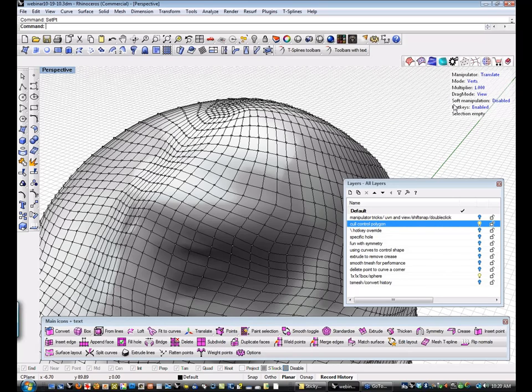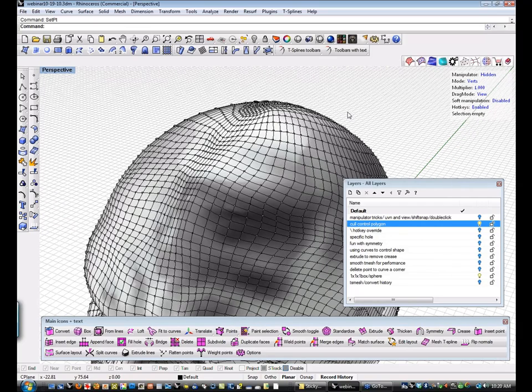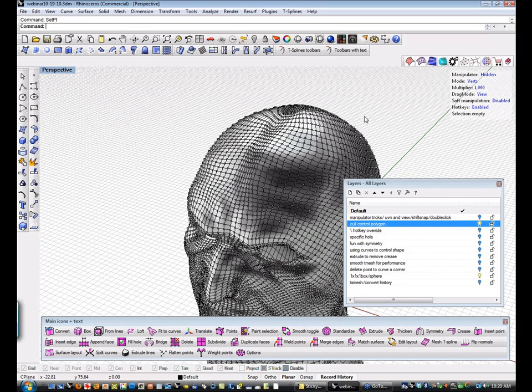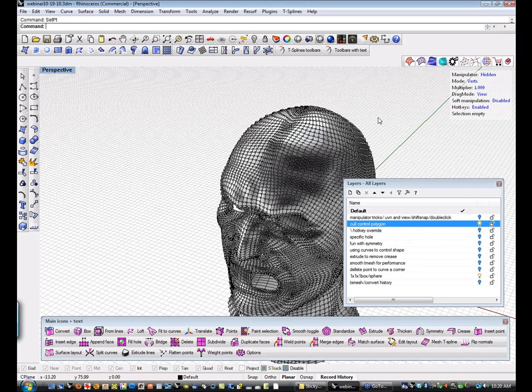The other way to do that is to hit control space bar, which shuts off the heads-up display, enter your Rhino keys, control space bar, bring your heads-up display back up, and that changes the priority between whose hotkeys are working. But the backslash key is a little faster, more efficient, and there was much rejoicing when the programmers threw that in, especially by me.